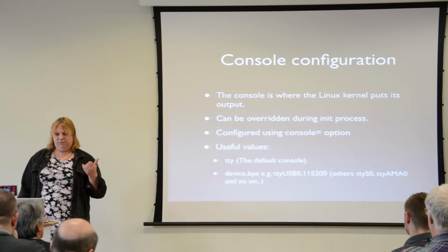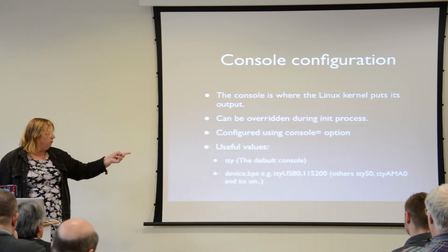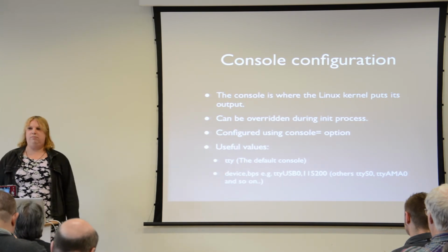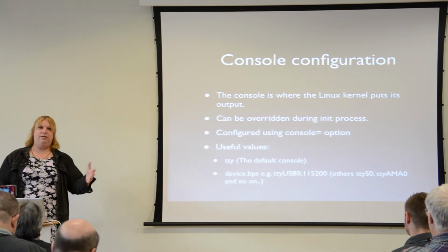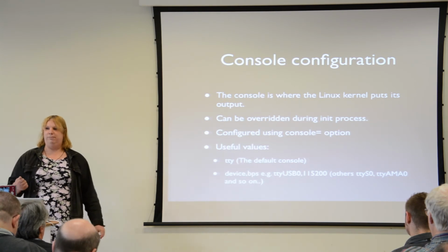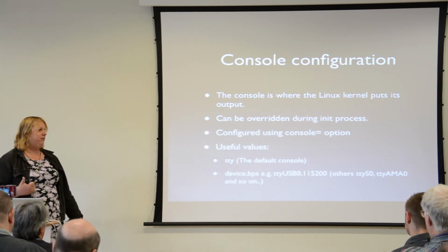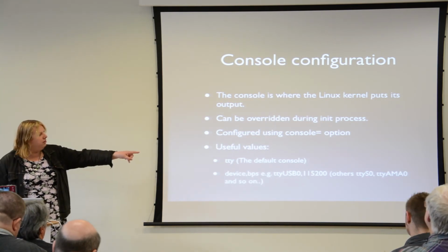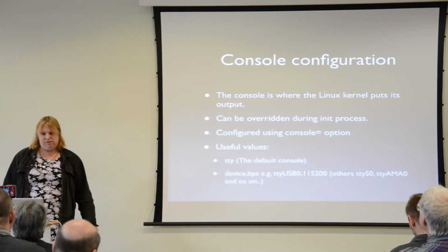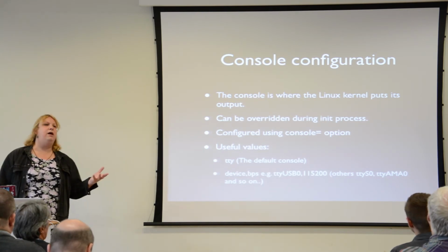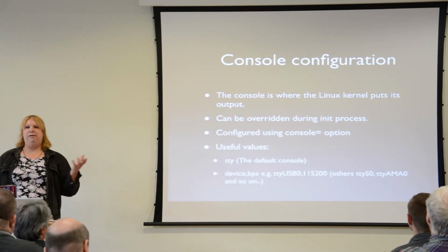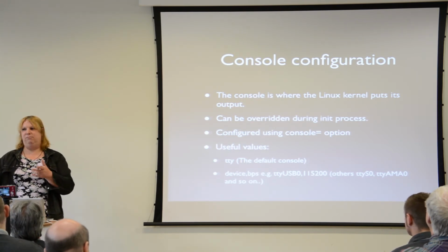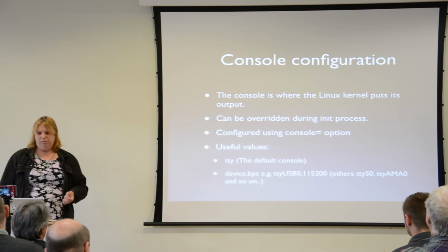We've got the default console. As I said, you could use a USB one. On a PC, you can use ttyS0 with a good old-fashioned tin box, which has actually got a serial port on the back of it, which there aren't many of around anymore. And so that's the ARM. The AMA is actually the ARM serial device. So you might get other manufacturers who've got a custom UART as part of their chip, with their own custom driver, so it might have a different name.